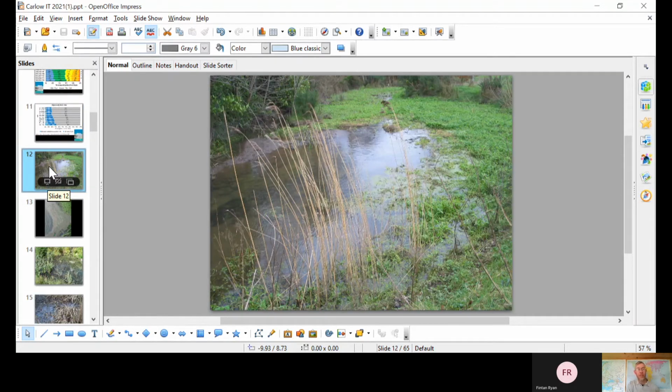Well, we can get clues from looking at natural environments. This is a stream habitat that we widened out into a buffer zone in East Cork, probably about 25 years ago. You can see the old stream channel here along the boundary, grand and straight, and we pulled out the area, planted it with various different wetland plants, and you can see this is 2 years on. There's a silt area that has accumulated here, so that gives us an immediate clue that the silt settles as soon as we create a space where the water can slow down a bit.